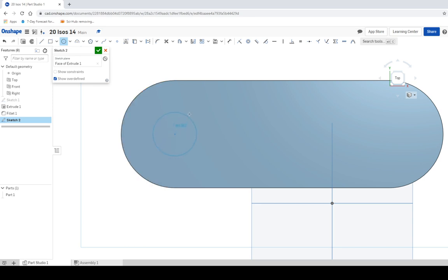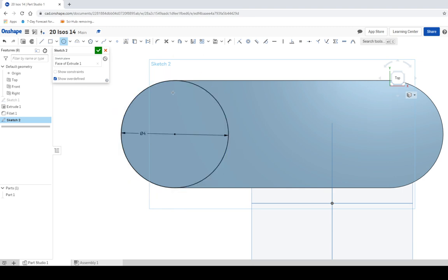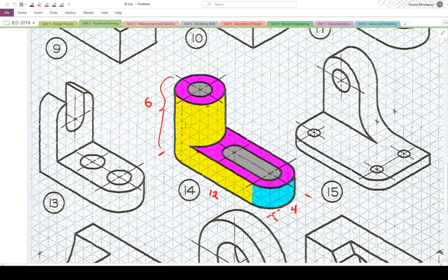Okay, so I can make a circle that goes out and reaches the end of the fillet. Now, it's not going to snap in place for me, but that's okay. We can just click the circle and then type in 4 for the diameter, because it's going to be 2 for the radius. Okay, that circle should go in exactly with the shape itself. We can also go ahead and make the second shape. Yeah, I guess we can do that. So we can make this second circle already, and we can just extrude this part up.